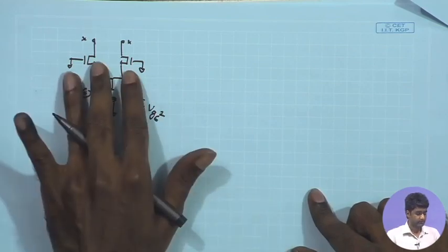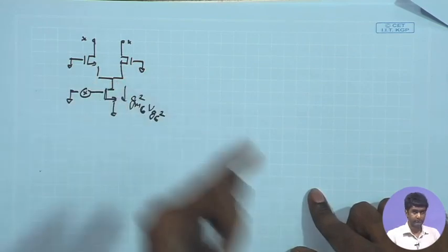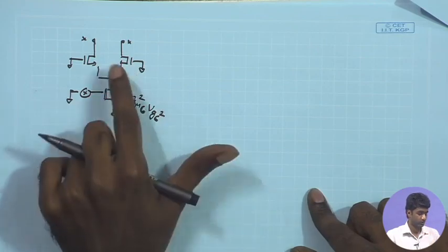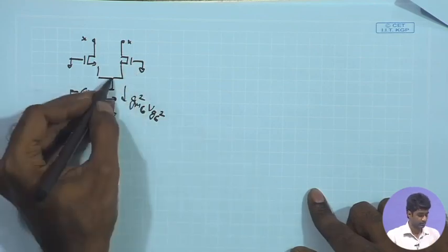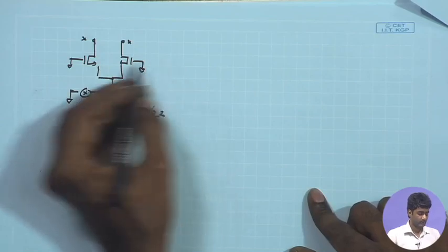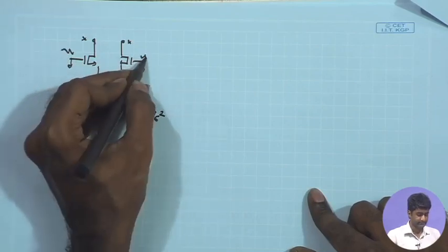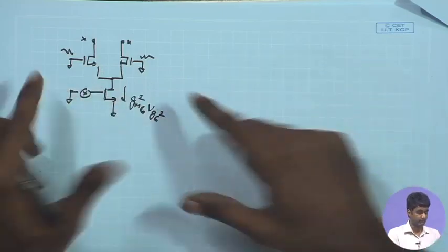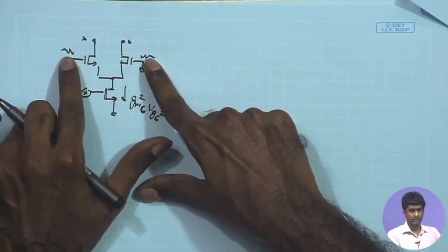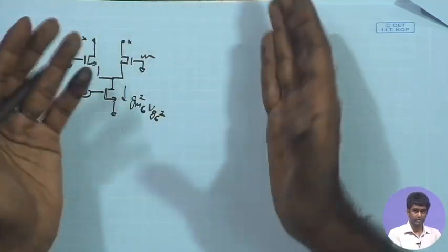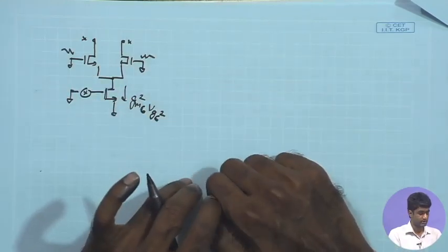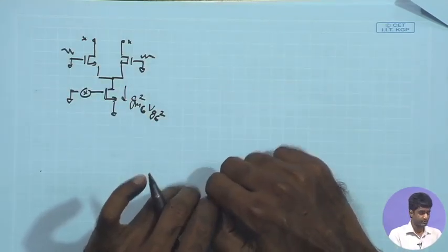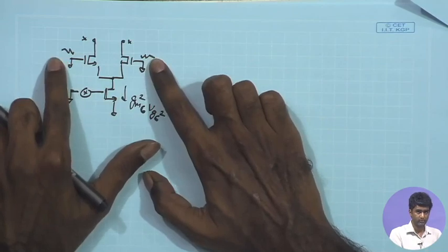Another important factor is we are using the differential operation only to figure out the overall noise, and the main issue there is that when we look at the noise signals at the two gates, they are uncorrelated, they are independent. So whatever input referred noise we calculated, they are coming from the two different branches. Each of the devices has different noise contributions. They are uncorrelated.